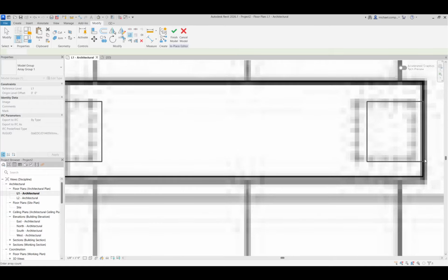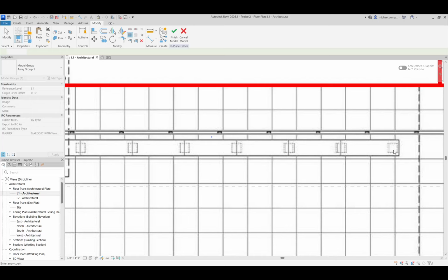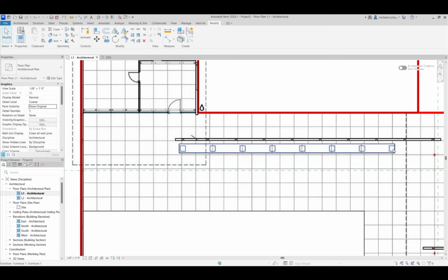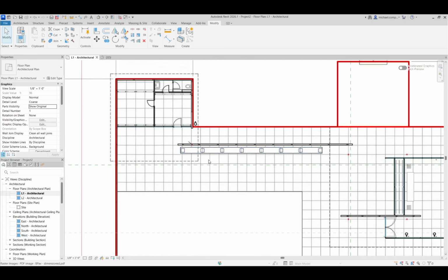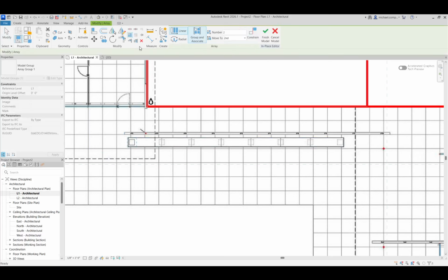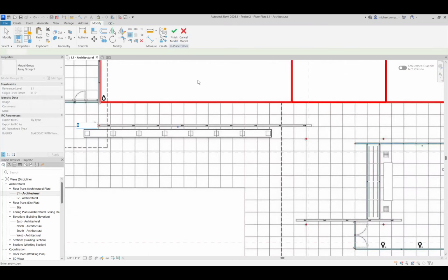And now look, it's different, right? Because of the trace, or sorry, because of the scan. So I prefer the first option. We'll finish this one out just so you can see where it landed. So it landed on that edge and it landed inside of that edge. So that's not good. I'm going to redo that the way I showed it to you before, which is the array, 8 elements, move to the last instead of the second, click that point, and the software does the math for me and lines them up beautifully.